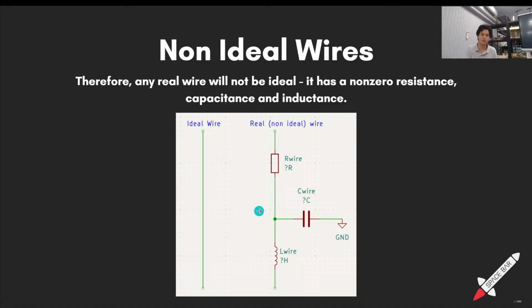And the capacitor can be to anything. In this case, I just put it to ground. Okay, this will couple to literally any other conductor. So if you got 10 conductors running, you have 10 capacitors. Then you have an inductor in series as well, which is the inductance of the wire. Okay, so now these are really ideal wires connecting these parasitic components, and now you're properly modeling the behavior of your wire in your circuit. Make sense? Transmission lines. No.